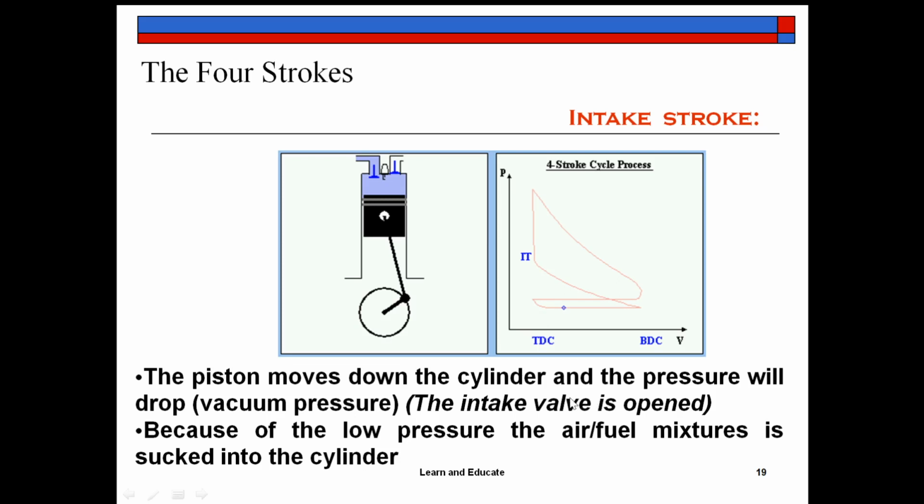The intake valve is opened. As a result of that, because of the low pressure, the air fuel mixture is sucked or taken into the combustion chamber or the cylinder. The portion above the piston is usually termed as combustion chamber. So the inlet valve will be opened as a result of the vacuum pressure created, and air fuel mixture will be taken in during the intake stroke.